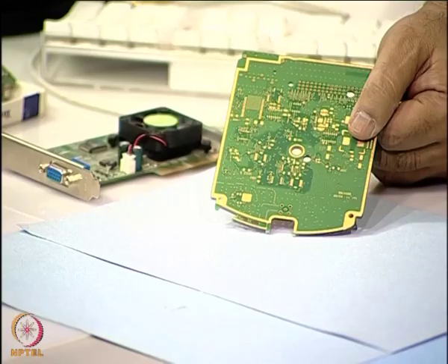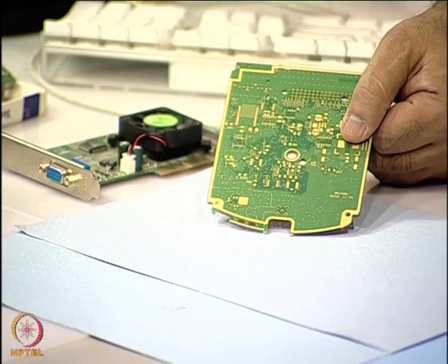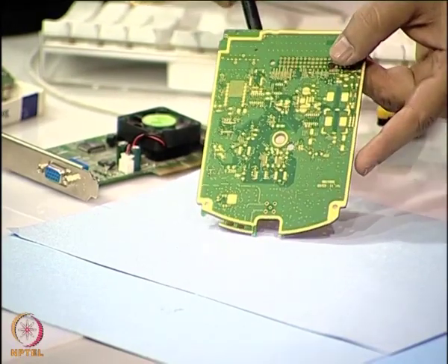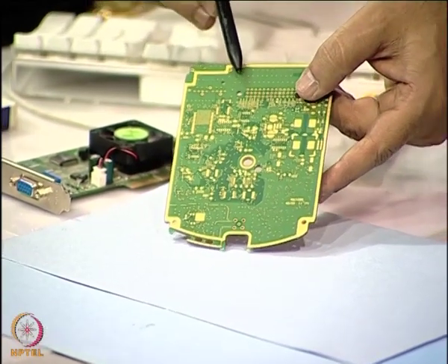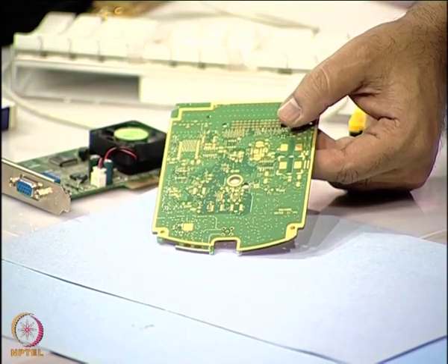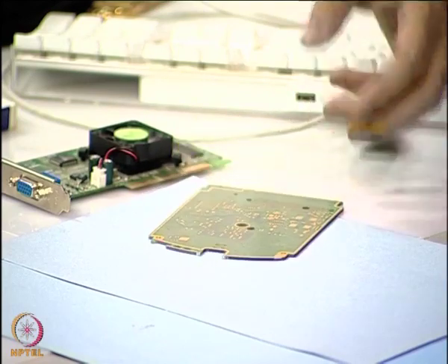If you look at this particular board, all the pad areas are open. You can see the gold color areas, these are the pad areas which are open on both sides, and other areas which do not have the component pad mounting are covered with a green paste material called the solder mask. Now, it is not easy to apply solder mask in the non-circuit areas without utilizing the layout assembly details. That is why we generate a solder mask pattern for both the sides of a double sided board. So, you will use photo imaging techniques to make sure that your pads are open, the holes are open, and all non-circuit areas are closed.